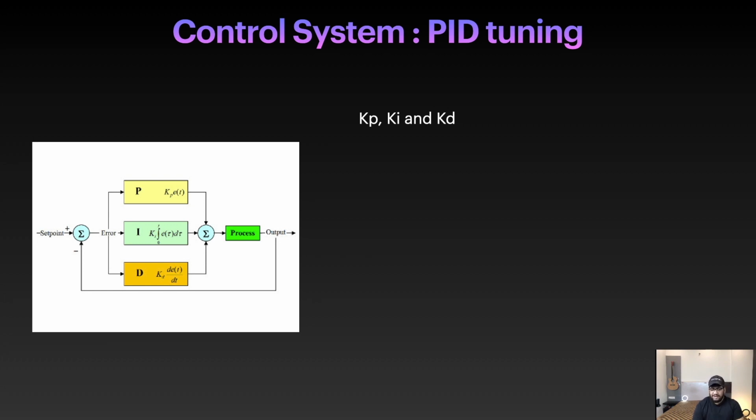So you need to definitely do PID tuning. Without PID tuning, you cannot have great results. You will have your error multiplied with a constant which is not good for the system. So ultimately, when you build the drone and flash the firmware, the last part you need to do is to fly the drone and see if these values are good. If not, then you need to change it. So finding the right value for these constants, that is called PID tuning.